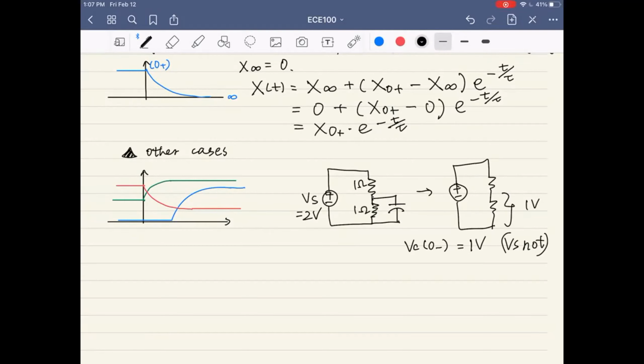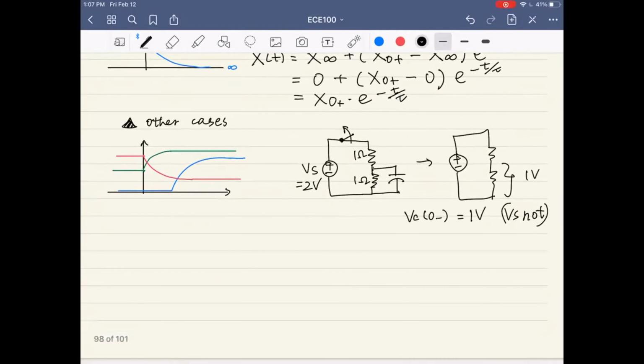And then suddenly the switch turns off. So the Vs is no longer delivering power to the resistance, right? And what we have here is a hanging 1 omega and a parallel 1 omega. Actually, we can see they're in series because no current flows this way, since it is already cut off.